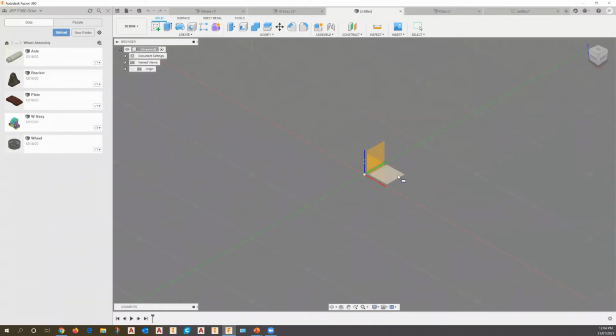So if I click to create a box on the XY plane, I simply click on this little yellow square here, and Fusion will say to me, okay, whereabouts do you want to place the first corner? Now, what you will notice if you're able to see on your screen, similar to what I've got, is a little marker in the middle here, which indicates the 000 point of my CAD file. Okay, and we're going to start our little box at this point.